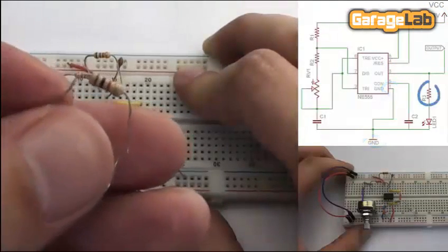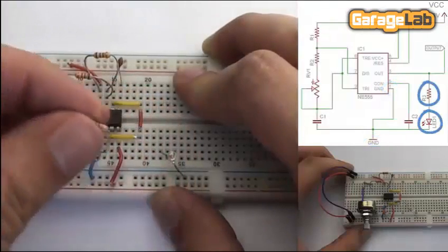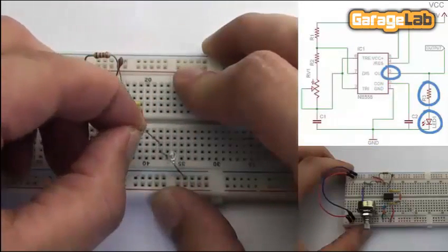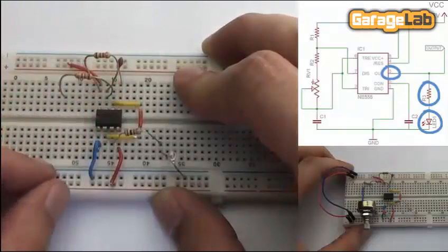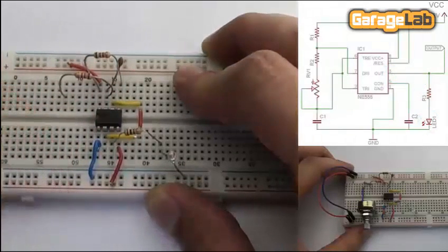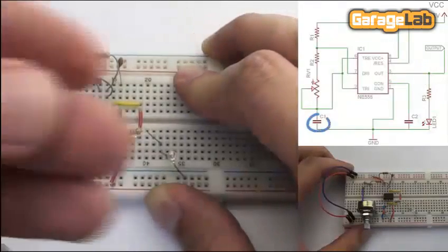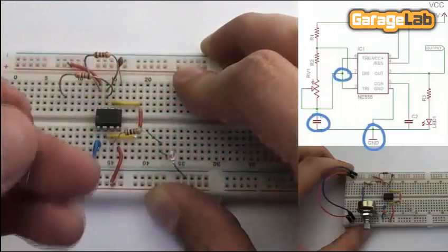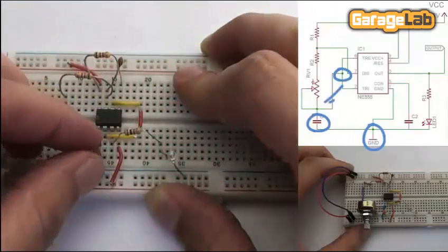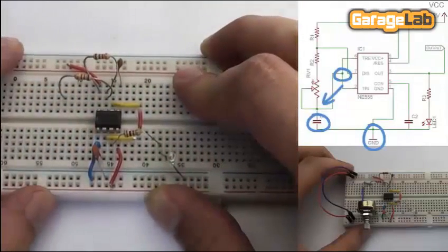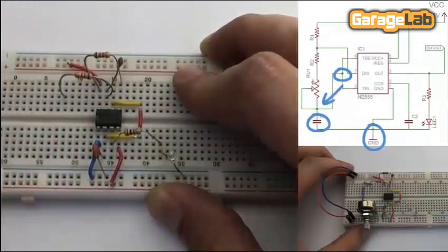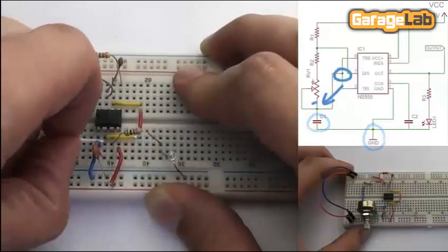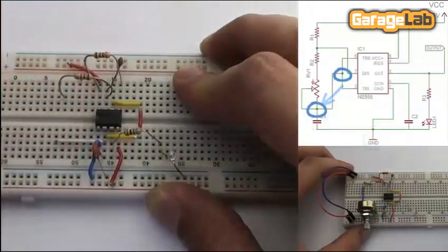After doing this, we connect one leg of the 1K resistor to the pin 3 and the other to the positive leg of the LED, placed aside as the video shows. The other LED leg goes to the ground. Now we connect the 100 nanofarads capacitor by putting one leg at the pin 2 and the other leg in the ground. Connect the jumper wire with one tip to the pin 2 and the other distant from the IC,